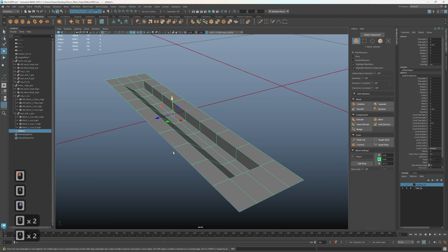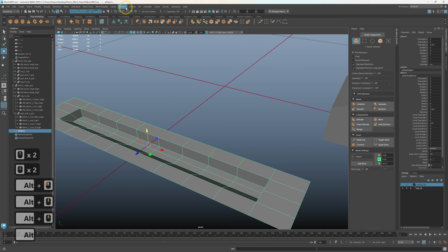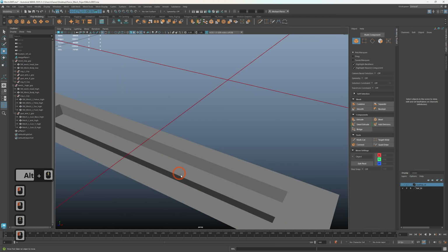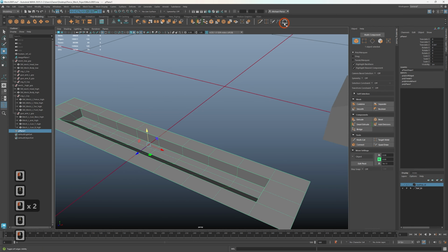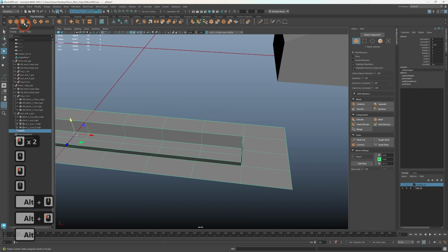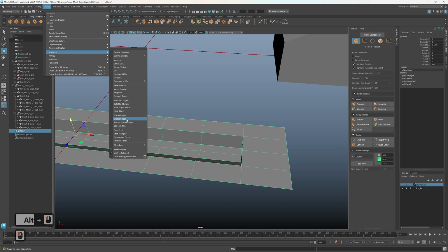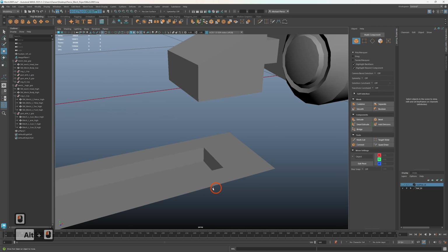Right, so now what I'm going to do is mesh, display, soften, harden, right? That way I get some different ones, and I'm going to use my shortcut. Again, that's under display, polygons, soften, harden edges, that way you can see them.